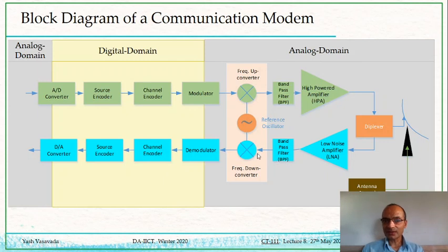You see, there is this oscillator, and this oscillator is generating cosine of 2 pi f ct and sine of 2 pi f ct. It is not made very clear here. It seems like this oscillator is generating only one signal, which is going here, but really it is generating both cosine and sine. If it can generate cosine, then generating sine is not that difficult. You just put a phase shift of 90 degrees, and that signal will then be a sine signal, a sinusoidal signal.